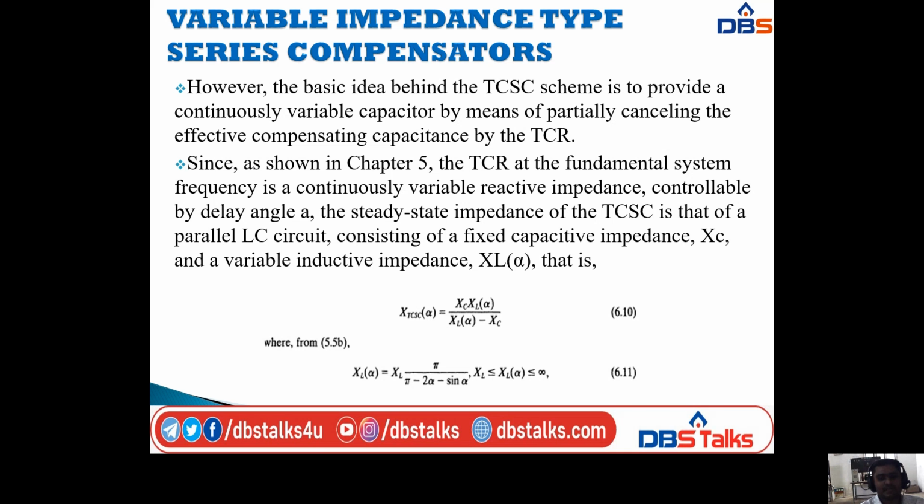Since, as shown in the shunt compensation concept, the TCR at the fundamental system frequency is a continuously variable reactive impedance controllable by delay angle alpha, the steady state impedance of the TCSC is that of a parallel LC circuit consisting of a fixed capacitive impedance, that is XC, and a variable inductive impedance, that is XL of alpha. That is, X TCSC of alpha is equal to XC into XL of alpha divided by XL of alpha minus XC.